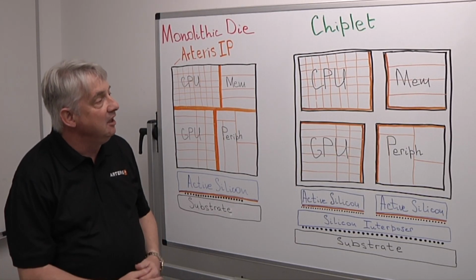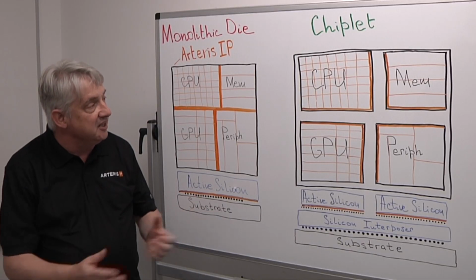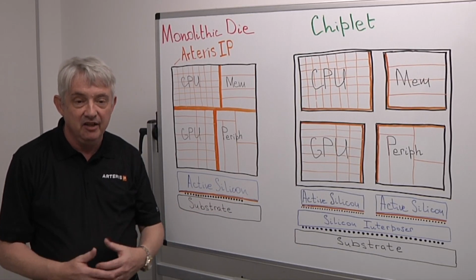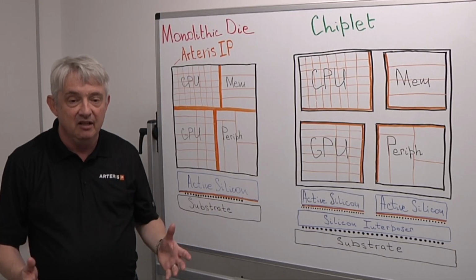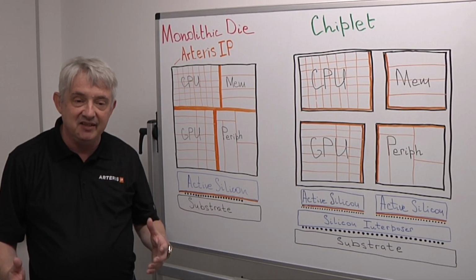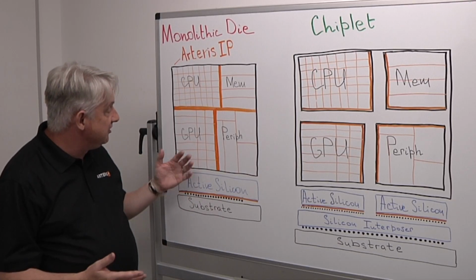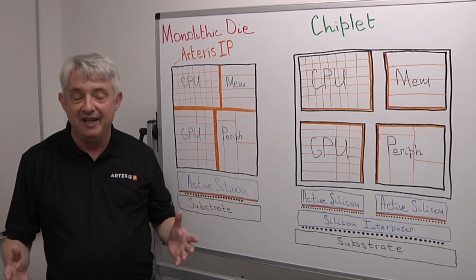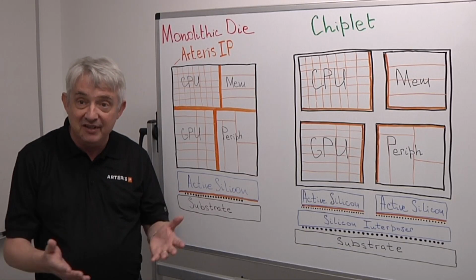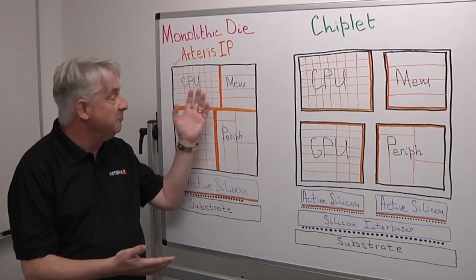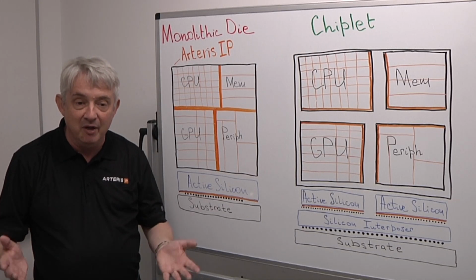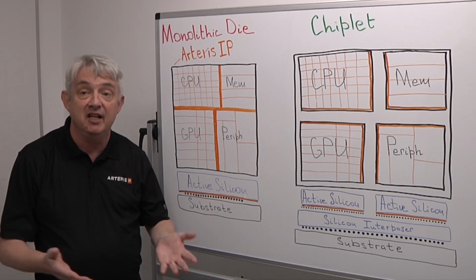Yeah, so as regards coherency, anytime you have caches that are sharing data, you're going to need coherency because otherwise you're going to have the wrong data. So actually, typically these days, your accelerator or GPU, most of the data will not be shared and can be non-coherent. But obviously there is some communication between CPU and GPU, and therefore that will need to be coherent. So you actually have need for both in most designs.